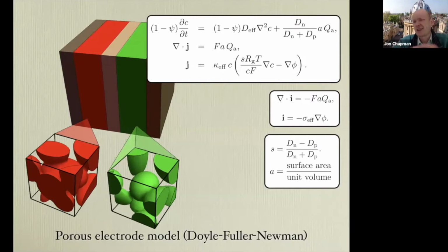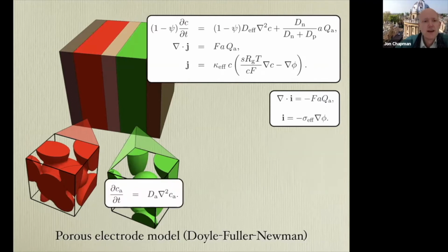My feeling is that it's not going to make much difference, and the degradation would make a much bigger difference to this surface area per unit volume parameter there, A. So you solve this at every point in the three-dimensional cube there, and then I've still got the Q there, and I have to tell you what that is.